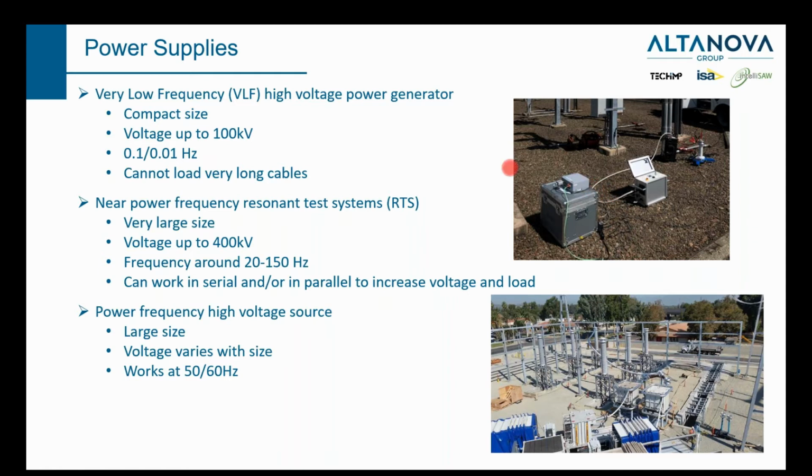The frequency is 0.1 hertz or 0.01 hertz, and the output waveform is also a sinusoidal waveform, similar to the power frequency, but the output frequency is 600 times lower. That's the reason the size of the VLF power supply is also much smaller and lighter than the power frequency power supply.